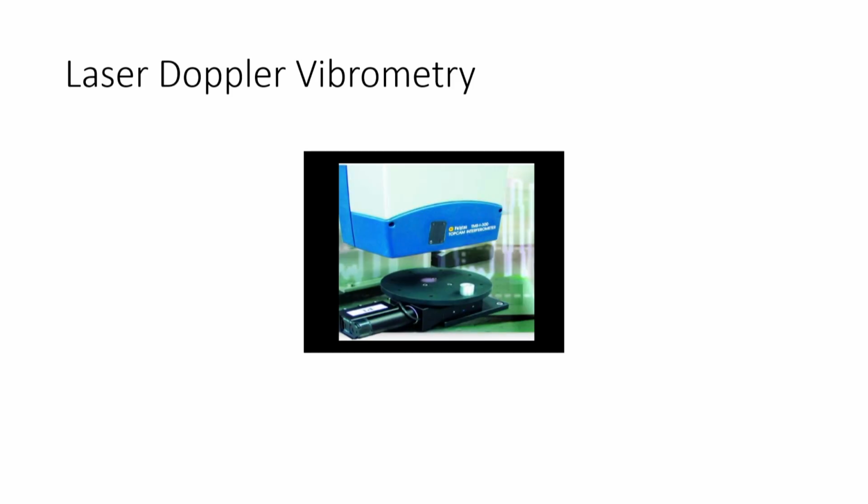Another optical technique I also want to tell you before ending these optical type of sensors, this is known as laser Doppler vibrometry. So, what it does is that it sends a laser beam, like let us say a particular laser beam is coming on an object, and the object here is actually getting vibrated, okay, with the help of some shaker. So, suppose there is an object over which the laser is getting dropped, and the object is sometimes here and sometimes here, because it is vibrating with certain excitation level, with certain amplitude.